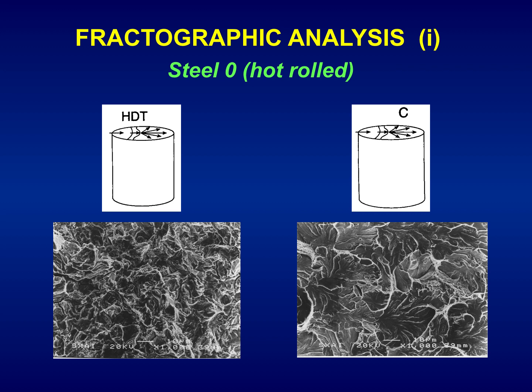Fractographic analysis for steel 0, hot rolled, not cold drawn at all, 0 degrees of cold drawing. We have a kind of hydrogen damage topography after the fatigue pre-cracking, and final fracture by cleavage. This hydrogen damage topography is the so-called tearing topography surface, with a kind of microdimple behavior, a kind of ductile appearance at the finest microstructural level.